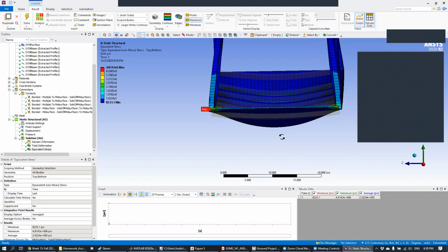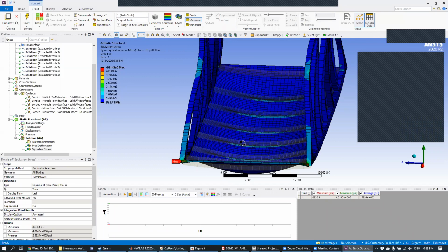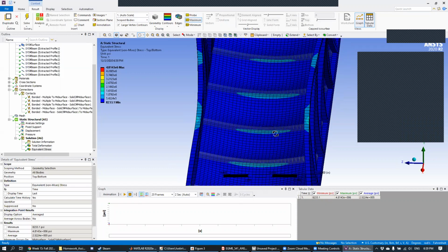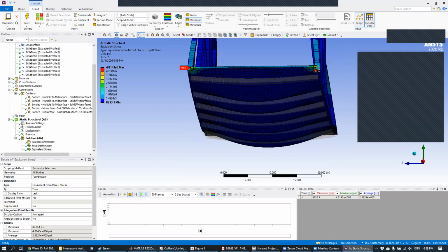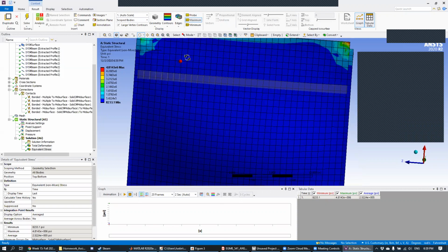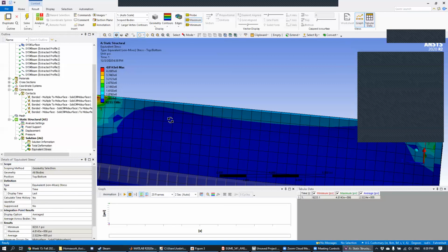All right, question. Do we need any mesh refinement? Yeah, actually, a good rule of thumb for mesh refinement is to look at the areas where you have high stress concentrations, and usually those are good areas for mesh refinement. If you look at this mesh right here, you can see that we have stress concentrations here and here at the edges of the domain. These are great areas for mesh refinement. If you wanted to, you can go in and refine around here, and you would get an even more accurate computation for the stresses. So yeah, that's a good point.